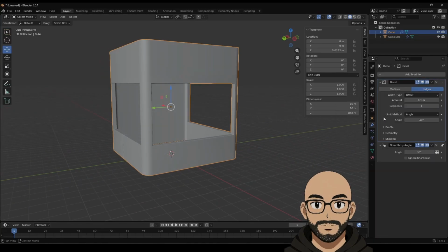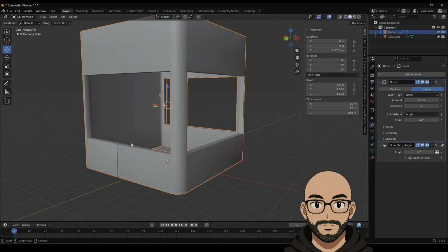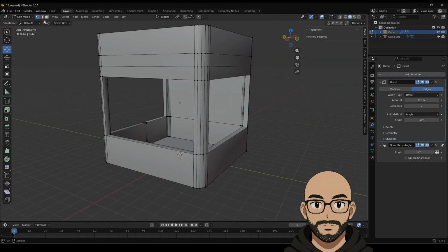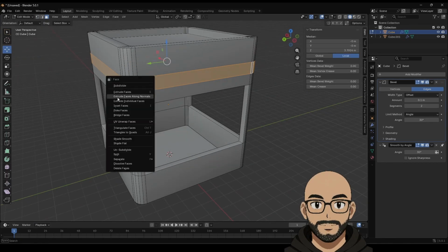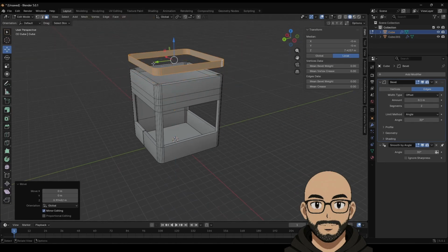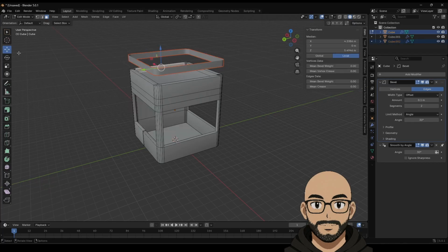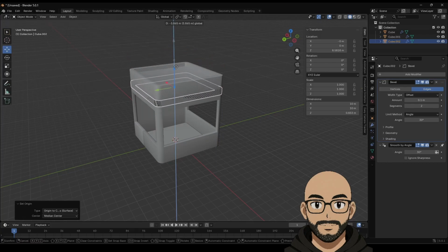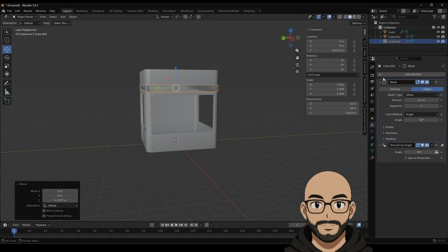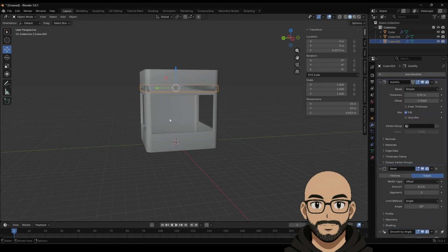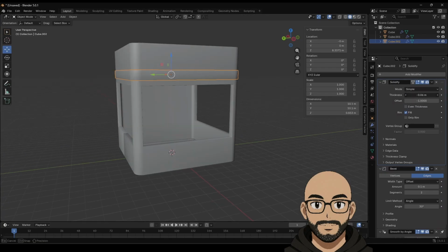generate bevel. Yeah, that looks nice. Now this piece up here, I actually want to say Shift D, like so. Then root selection, center to mesh, move this down, and I can move this up and down wherever I choose, is fine. And then if I solidify this, there we go.